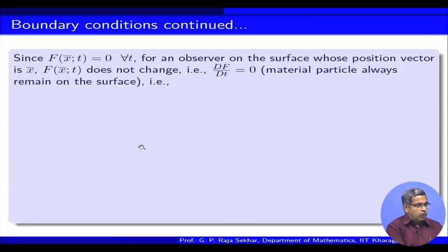Now, one assumption we use is, if you have a free surface, whatever particles are sitting on it will not leave. Okay. This is the kinematic assumption. What do you mean by that? You can see if you drop some particle, it will be oscillating like that. They are not escaping unless you give some large external forces, right.